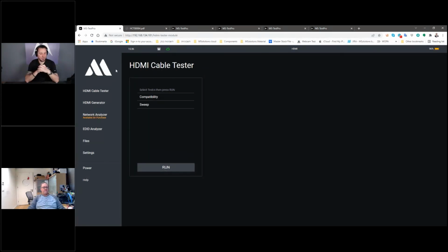That's great. Sorry, I was just, I always recommend, because it only takes a few seconds, I always tell people run both tests. That will give you the complete story about that cable. If you don't run both tests, you might have some issues later down the line. So for the few extra seconds it takes, always run both tests. Yes, and if you want to generate the PDF file, you must run both of them. You have to do both. Yeah, exactly. Otherwise, it will not provide you the ability to save those PDF files.